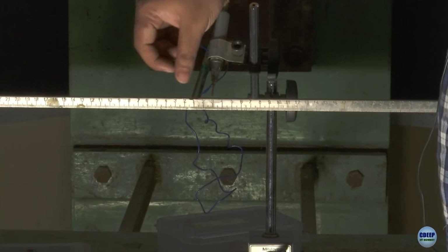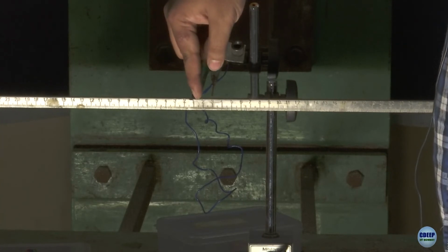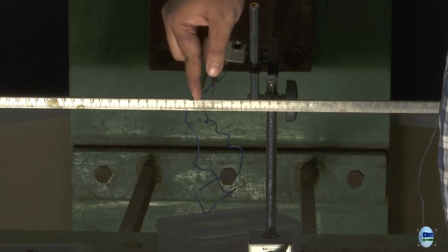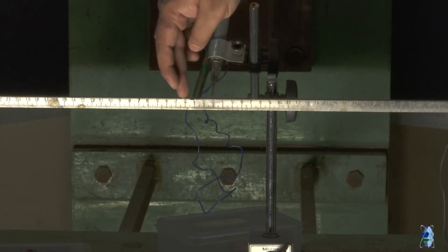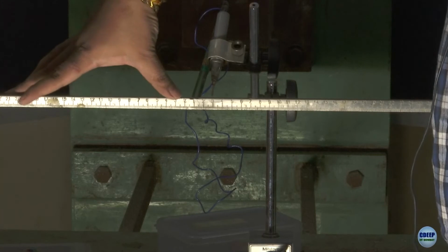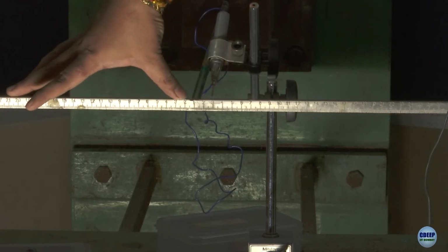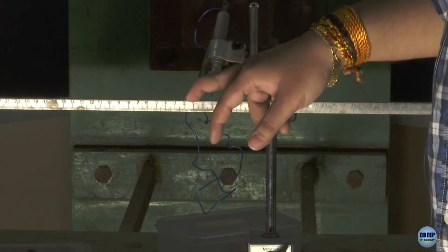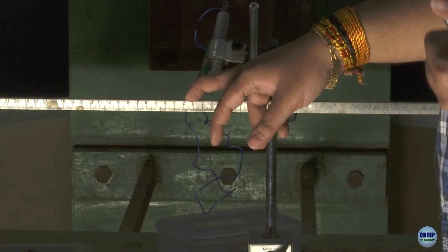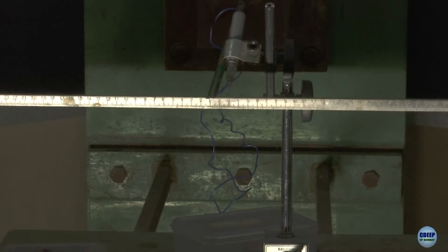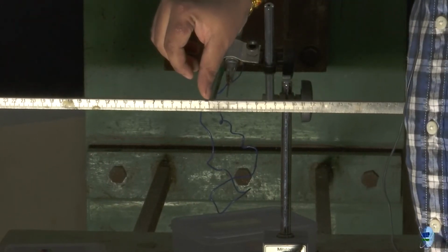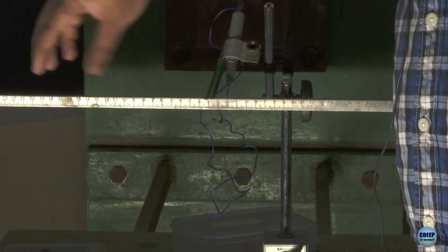As you can see, there is a scale attached to the bar at the end of the beam. This scale starts from 1 instead of 0, and there is a scale on the left side of the bar as well as on the right side of the bar. In the manual we have to calculate two values, A and B. A is your distance from the free end to the point where you apply the load.